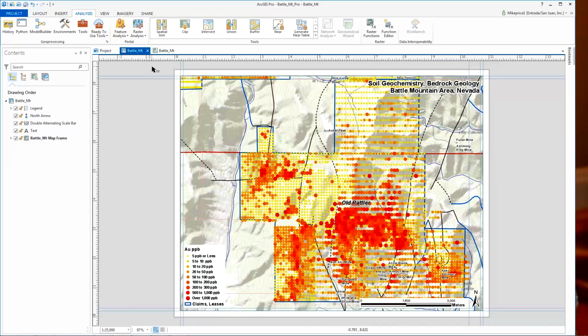Sure. Actually, when you license an Esri product at the basic level, the standard level, or the advanced level, your license is shared between desktop in the version 10 world and Pro. So you'll have a license for ArcGIS that will run both a desktop install and a Pro install. And I run them side by side on the same computer all the time, and no problem. But again, if you're using concurrent licensing, you'll probably want to work with your license manager to make sure that you're able to share properly, and especially if you get into editing, be able to edit concurrently.